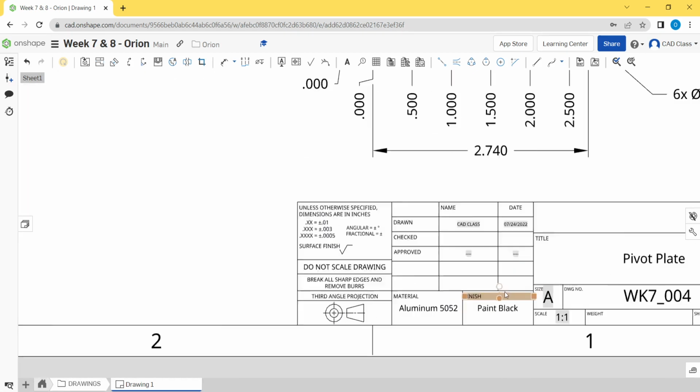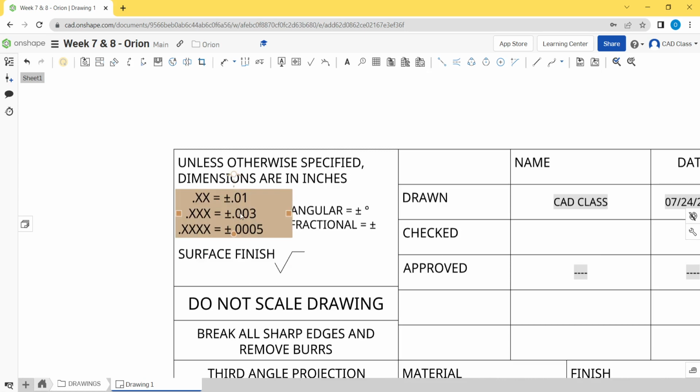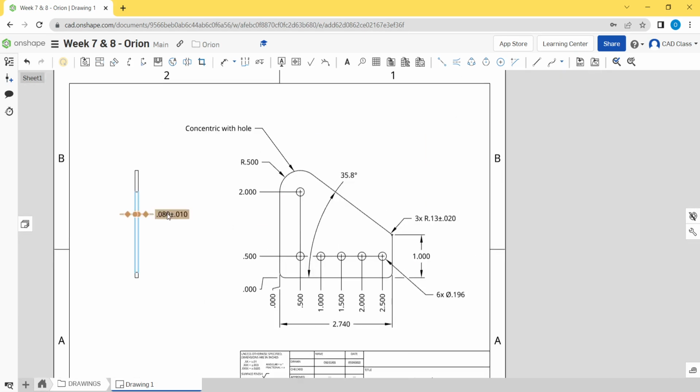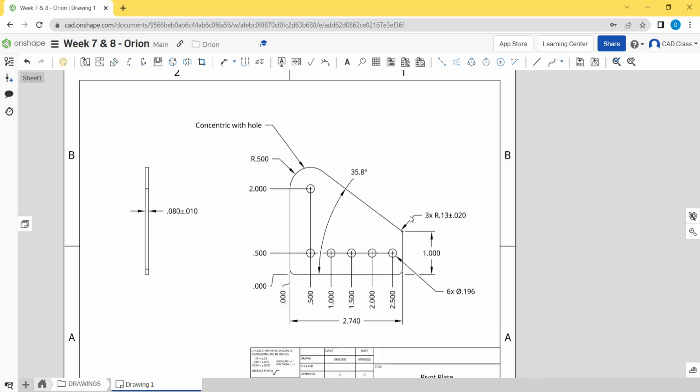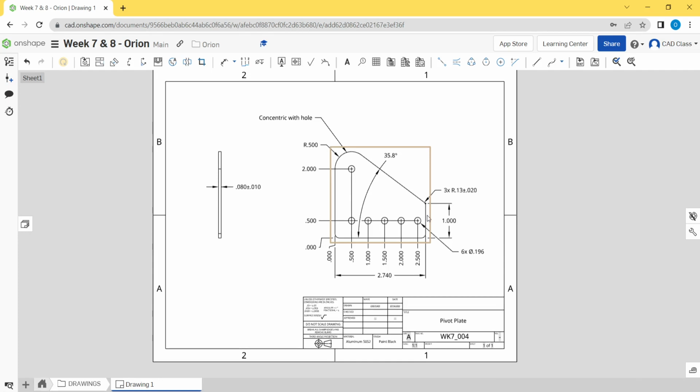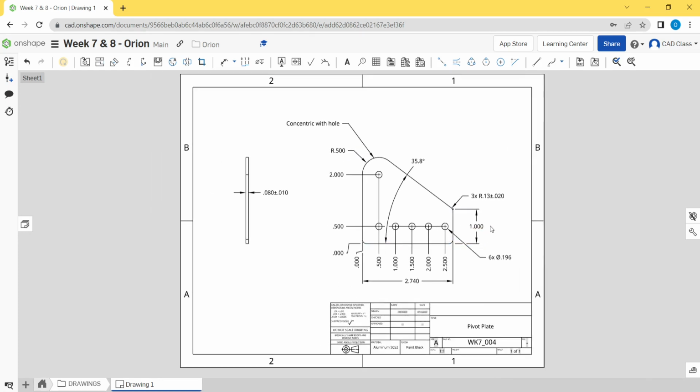Generally speaking, when you're building a template or something, you want your sheet tolerances to be pretty loose, and then you specify tolerances that are more precise in the specific situations where you want. In terms of specifying tolerances in the context of FRC, it just does not matter. We are not going to check tolerances specifically during the season. What we will do is test fit the part on the robot, and if the part fits correctly and performs the function it's supposed to, then it's a good part. If the part does not fit, then it will need to get adjusted or remade.